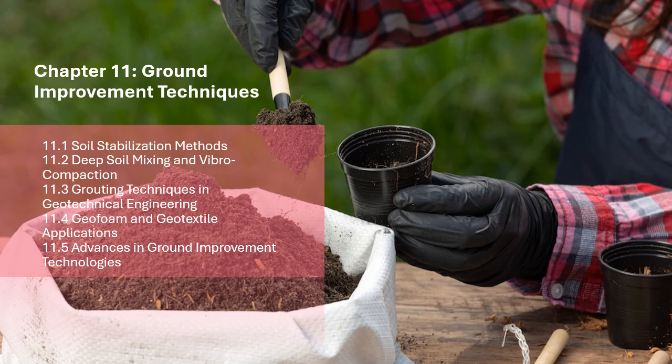1.5.1.2 Nanotechnology in soil stabilization. Nanotechnology has brought about innovations in soil stabilization by introducing nanoparticles into soil matrices. These nanoparticles can enhance soil structure, increase its strength, and reduce permeability. Nanosilica and nanoclay materials, for example, have been shown to significantly improve the mechanical properties of soil when applied at small dosages.